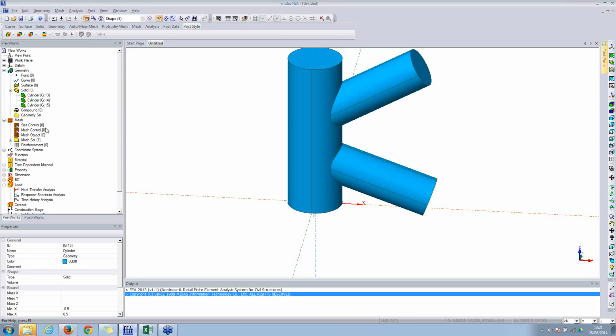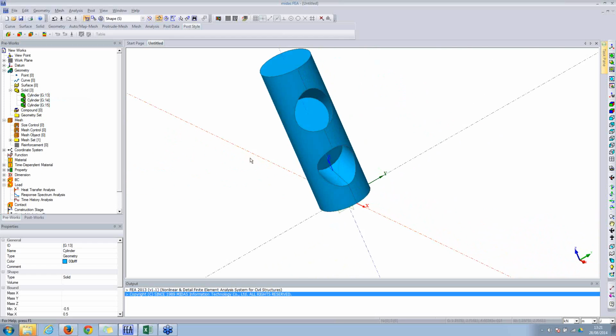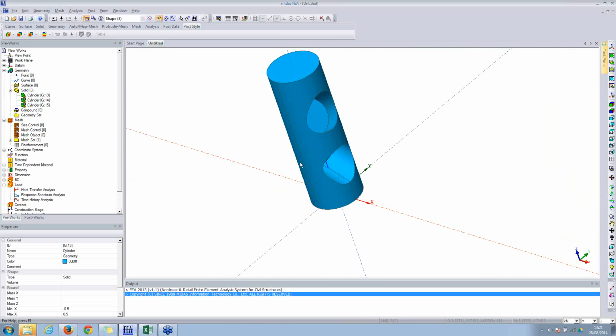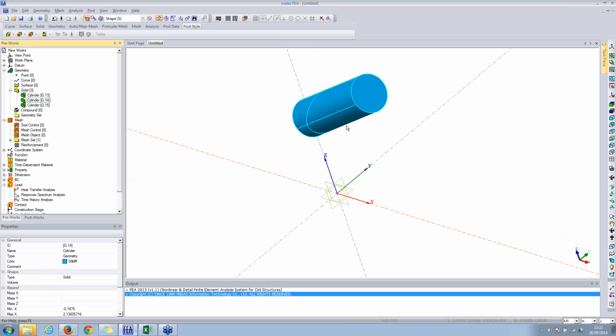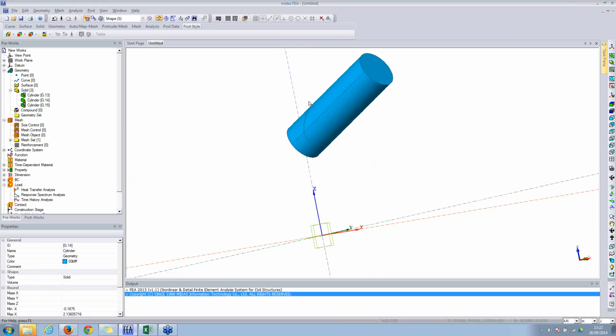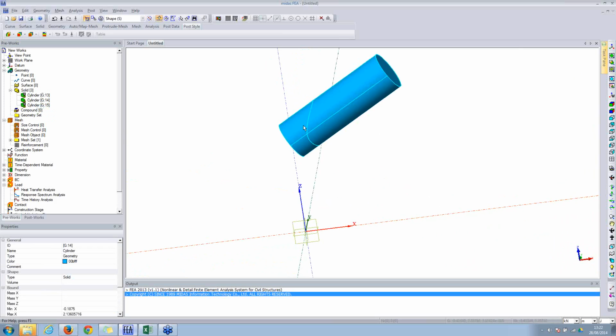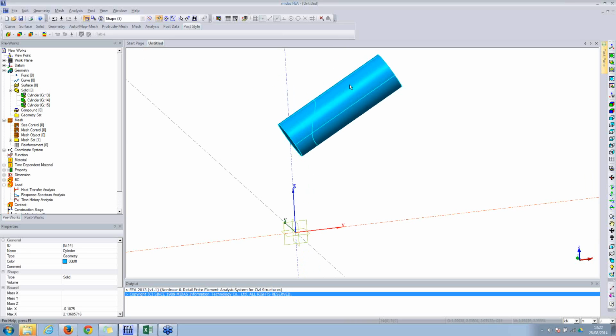Now if I display this show only, we've got this shape. So I've got the imprint here. Why did I need this imprint? Because I'll be deleting this portion, the left hand portion from the diagonal, because there is no diagonal member going inside the column. It's all welded on the outside.